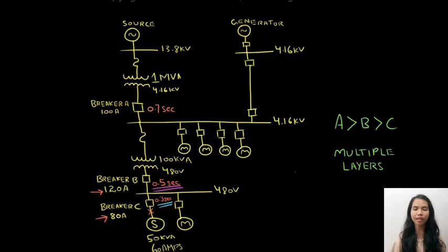The disadvantage of the strategy occurs with high current levels, if we consider a three-phase fault at the 4.16 kV bus which produces an abnormally high current. This strategy may not provide good protection because it uses definite time delay, and to make coordination possible, each layer of protection has some delay.